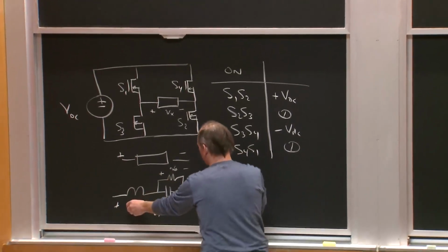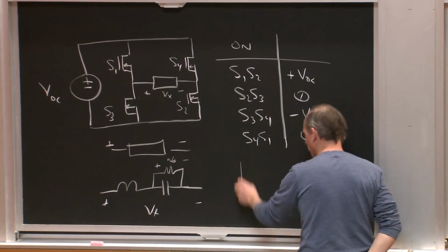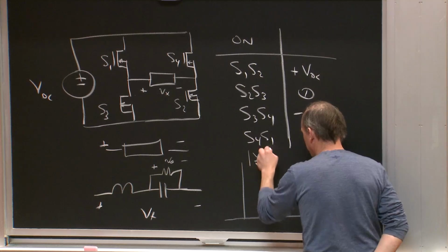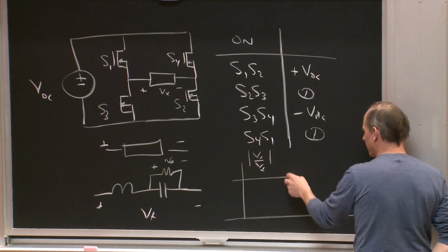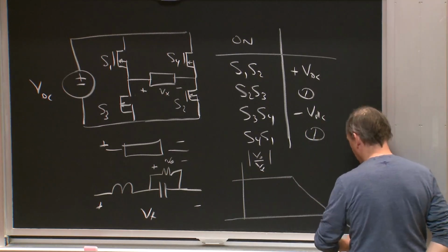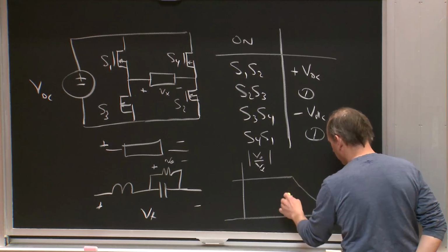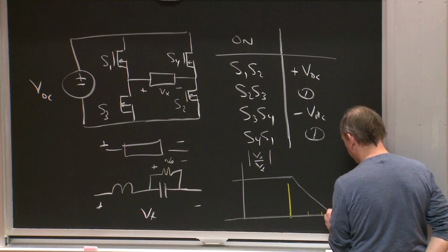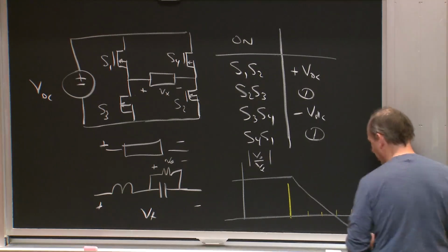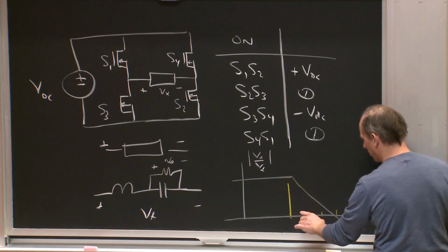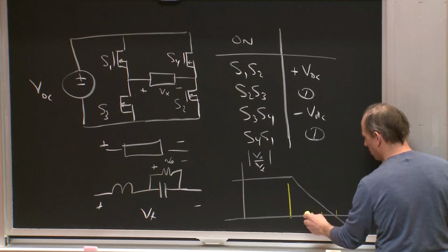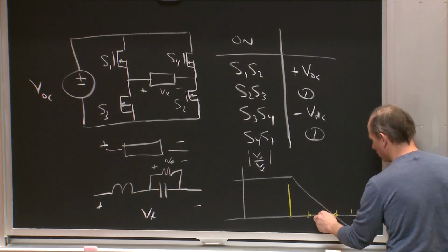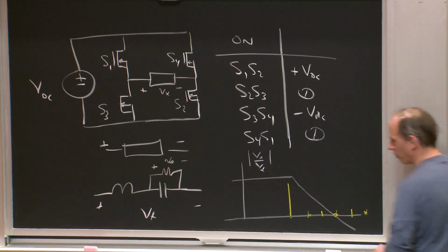So if I think of the transfer function from Vx to Vo, the magnitude of Vo over Vx, ideally there's going to be some kind of low-pass filter where I want to put the fundamental in the pass band, but 2, 3, 4, 5, 6, etc. I usually only want this component, and I would like to filter everything else. We can get rid of these by the half-wave symmetry, and then it's just a question of what about third and fifth and so forth.